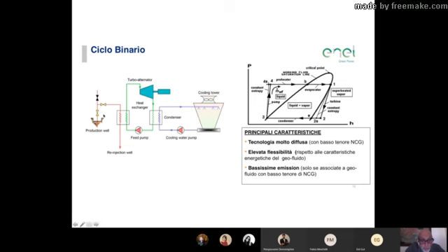How does it work? It's very simple. From your production well, your water plus bubbles usually go into a first heat exchanger, and you exchange the heat from your hot geothermal fluid that comes in to a secondary fluid, usually a low boiling temperature fluid, usually a hydrocarbon, and then the vapor of this secondary fluid, you run it through the turbine to produce electricity.